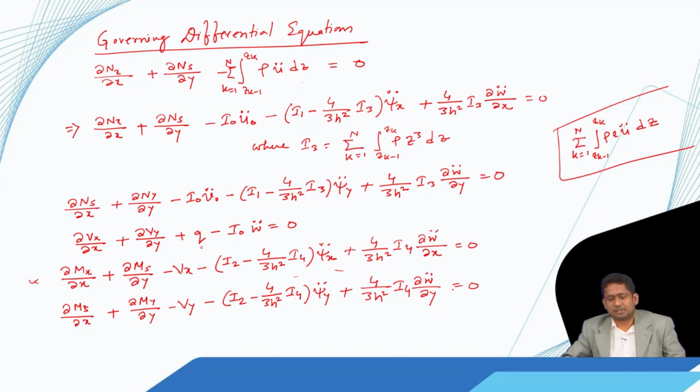We can directly solve the governing differential equation. For that if we want to do a Navier solution, our lamination sequence and the boundary condition has to permit that. In that case, we do separation of variable and write the x and y dependence of the solution variables as double trigonometric series, and then we put it in these equations, and then we separate out the trigonometric terms and the rest of the algebraic terms are set equal to 0, and that gives us the solution. We can do Navier type solution if we can, and otherwise energy or virtual work based solution is always possible.